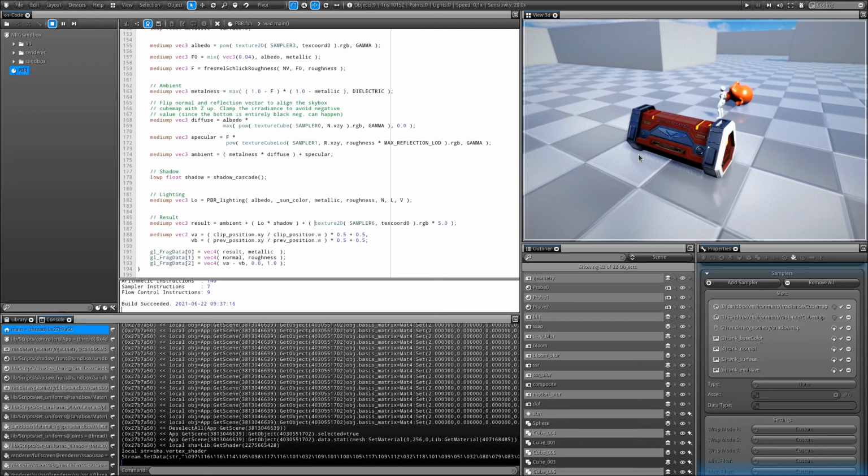Now, every time you're going to import an object that has the identifier _prop, it will use that preset that you have created. So when you're creating your preset, ensure of the type of material that has been created using your 3D creation software, regardless if it is Blender or Maya, because every time you export a DAE, the material identifier will be exported as well.